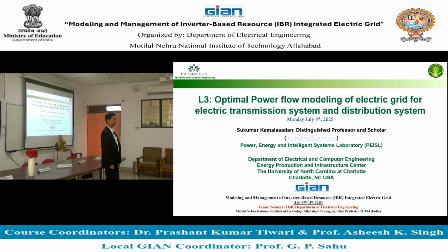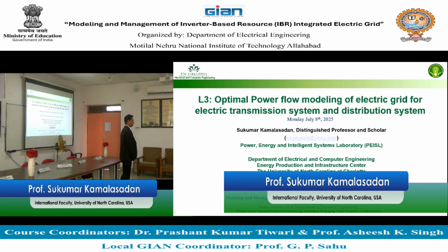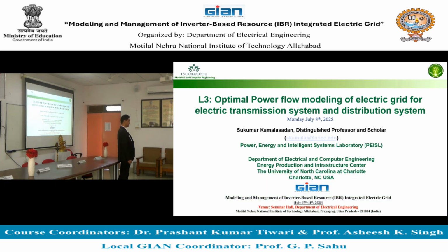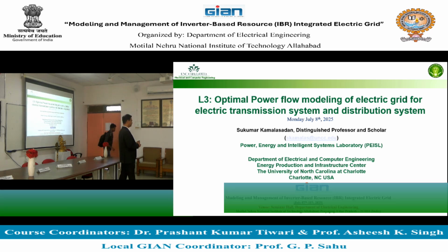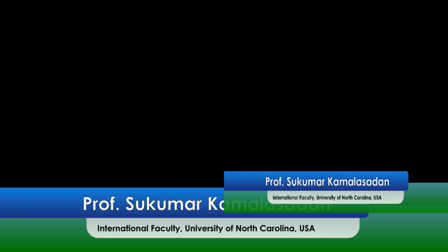Power flow models are used to study the electric grid, power flowing from point A to point B, by calculating the voltages at different points on the grid and then finding out how much power will flow from point A to point B. We studied these power flow models for the electric transmission system and then the electric distribution system. So these are the things which we studied yesterday.